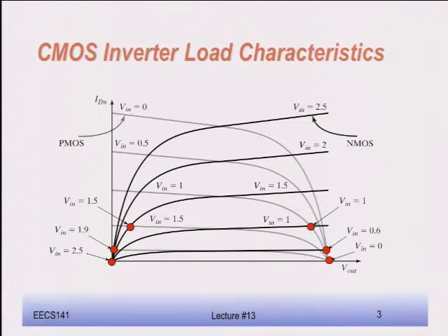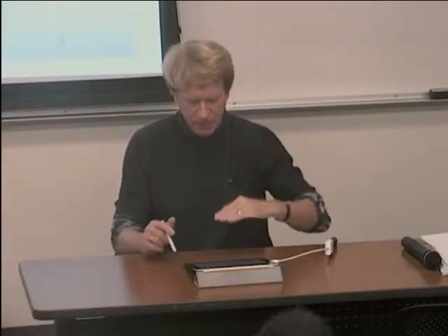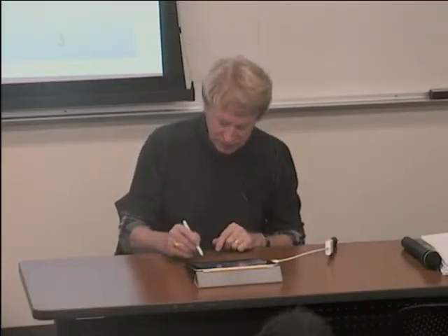Then if we start increasing the voltage, we gradually turn on the NMOS, which is going to be in saturation at that point in time. If Vin is low, the output over the NMOS is going to carry a very large voltage, and as a result is going to be in saturation, while the PMOS carries a very small voltage over the drain to source, so it's going to be in linear mode.